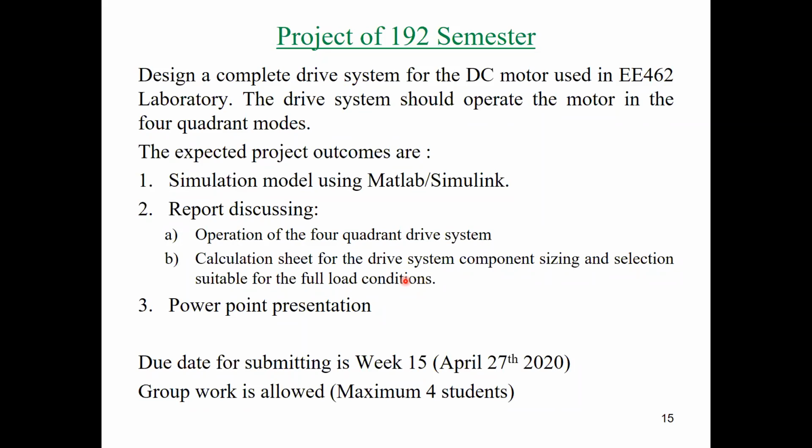And we can control the voltage using the DC chopper. What is the supply current? It is based on the machine current and your calculations, based on the full load condition of the machine. So this is called the calculation sheet for the operation of the machine. And for the sizing, I mean, sizing means in order to buy these values from industry, what will be the values? For instance, I'm going to buy a source, so I have to specify the voltage.